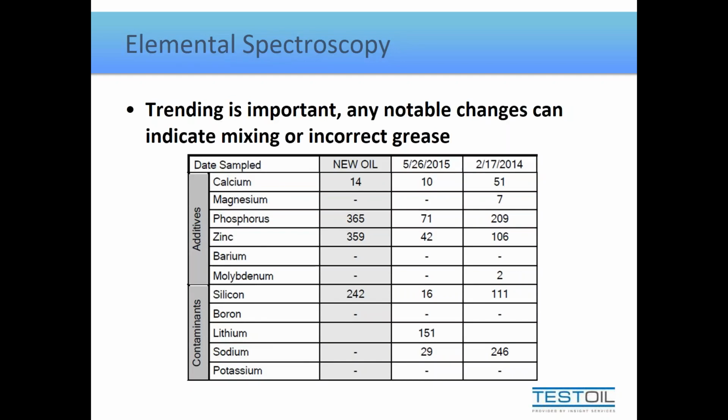This is suggesting to us we've got a mixture of greases going on here, and somebody is adding in a lithium-based grease. Well, there may be compatibility issues just between the thickeners, but the big thing is that probably explains why the anti-wear isn't there. They're not using an anti-wear additized grease anymore.